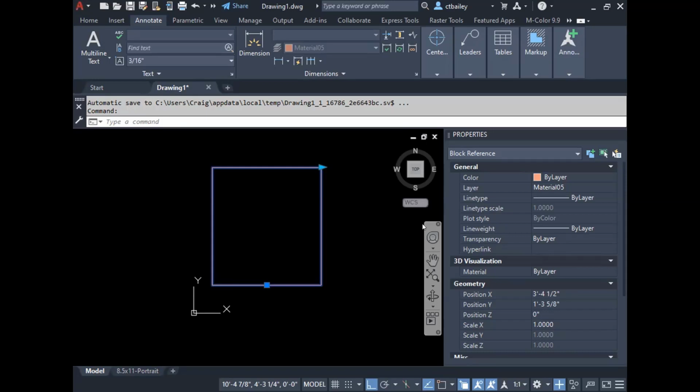Zoom this down. C space E. Stop. Take this hand, leave it on the keyboard. That hand, leave it on that mouse. Right mouse button acts as the enter key. Now, do not let that hand come off that keyboard. Everything you type, you need to do with the left hand. Don't hit the other key. Right mouse button. Now, show me the stretch action for your width parameter.